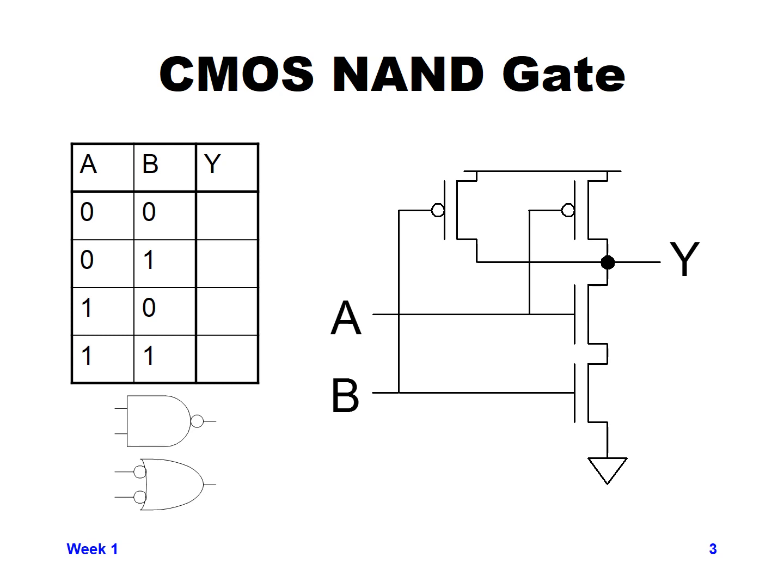The inputs went from no bubbles on the input to bubbles on the input, and the AND went from AND to OR. So that's using De Morgan's rule to change how you think about the logic. Transistor-wise, it's exactly the same transistor function, and you will get the exact same function out of both of those symbols. That's how De Morgan's rule says that the NAND is the exact same functionality as a NOT OR.